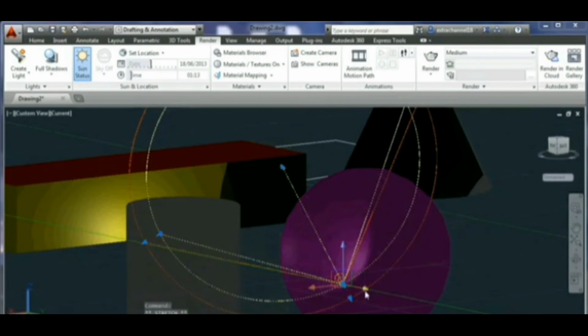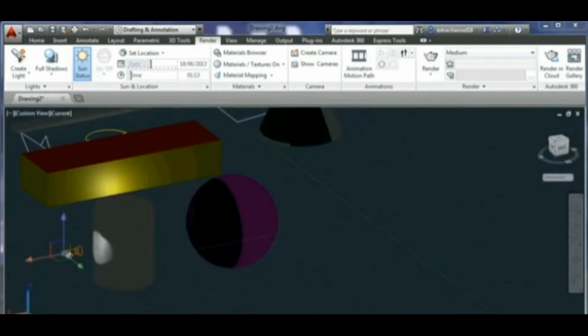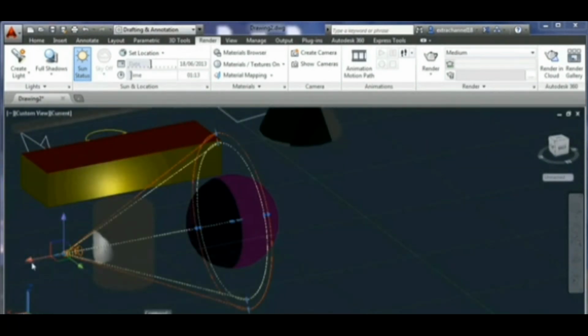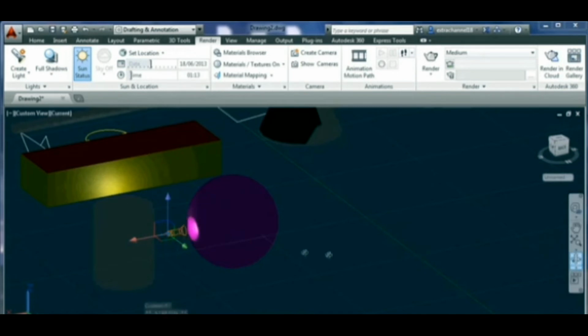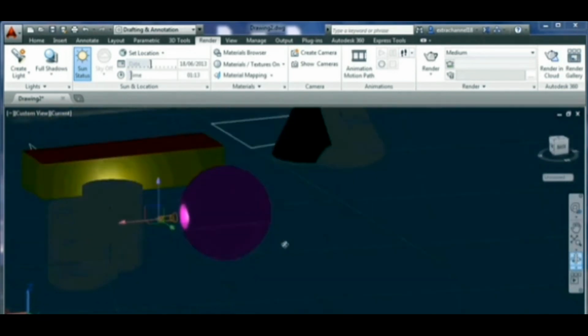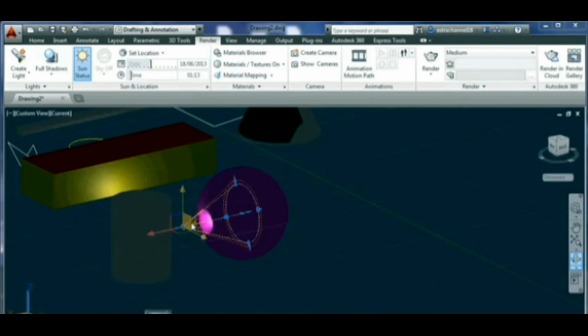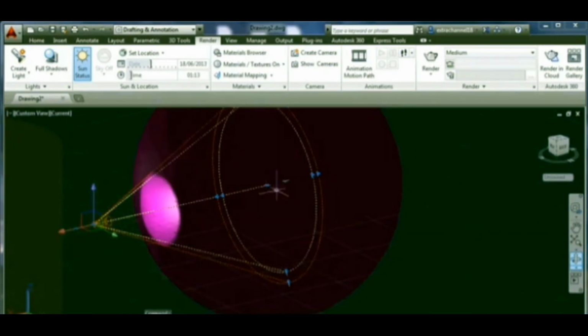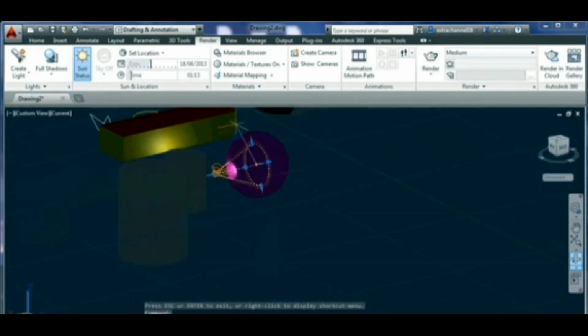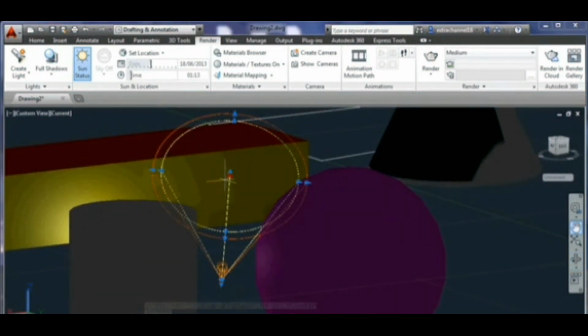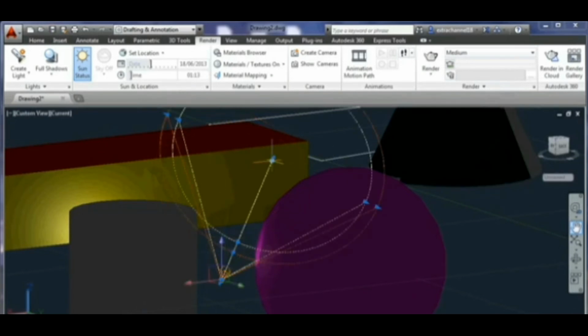You can move this kind of light exactly like the point light, but here you can set the direction and the radius as well. Just select the torch symbol and edit it. Just don't get confused. While editing the light, often check it and change the point of view. Remember that the perspective is ignored when editing the light through its blue points, unless you choose hot points, like the vertices of a box. You can choose also the Modify section to edit and move it.